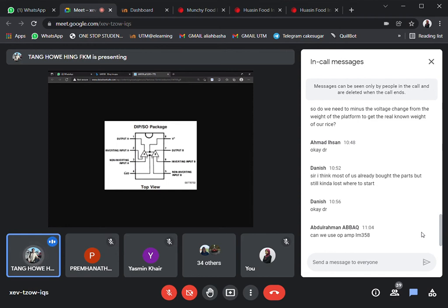Therefore, in that case, most probably you need to offset your voltage rather than at the 0 volt. So now you are going to offset maybe to 3 volt. Let's say all of the batteries actually give you 6 volt. So that means you need to offset your voltage up to 3 volt. So 3 volt will be your reference of virtual ground, and ground will be 0. And the ground essentially will be, in meaning, negative 3 volt.